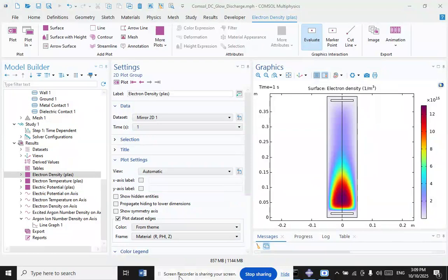Glow discharge is a type of plasma that is generated when DC voltage is applied to the electrodes inside a gas tube containing precursor gas in the pressure range of 0.1 to 10 torr. The type of plasma gas used and the process pressure to be maintained determine the minimum voltage required to maintain the discharge. There are different types of glow discharge, such as hollow cathode discharge, Penning glow discharge, and magnetron discharge used for deposition. Glow discharge has potential application in surface modification of polymers.